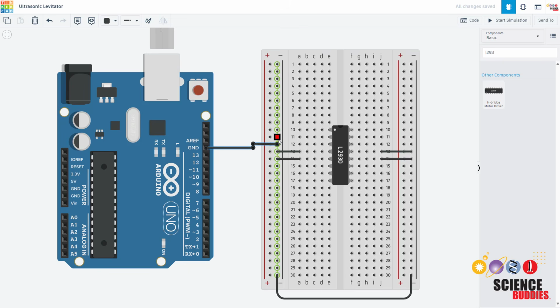So it is important that your entire circuit have a common ground. When we get into higher voltage power supplies later, it is important not to short circuit the power supply voltage to the 5 volts from your Arduino, so we are going to keep our power buses separate for now.